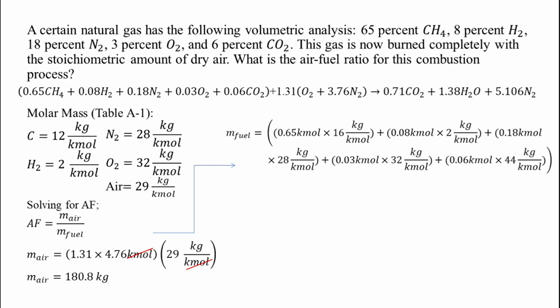plus 0.18 kilomole times 29 kilograms per kilomole plus 0.03 kilomole times 32 kilograms per kilomole plus 0.06 kilomole times 44 kilograms per kilomole. We cancel the unit kilomole. The mass of fuel is 19.2 kilograms.